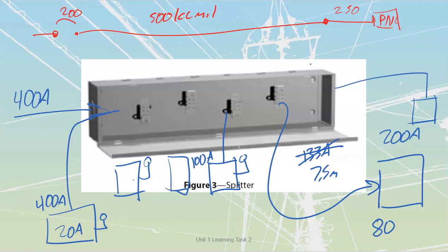Okay, there is a thing in your binder here, right above there, the paragraph above. It says a splitter must be used anytime that connection of more than 2 conductors of number 6 or larger is required. This is not true. Sometimes we are required to have a splitter just so that we can terminate the proper number of conductors underneath it. But the splitter itself is not the only way. We do have these other insulated lugs that we are going to utilize as well.